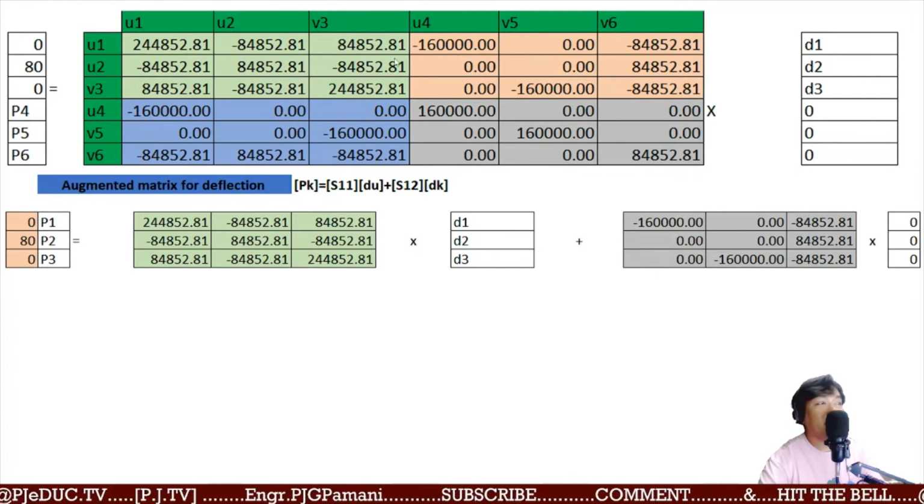Take this matrix times this matrix, plus this matrix times this matrix. I said U4, 5, and 6 are 0 because there is no deflection at those nodes or axis forces. So basically, that is removed.